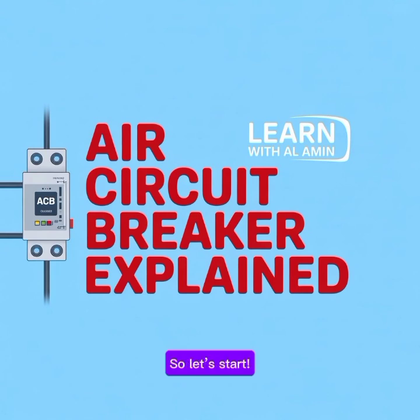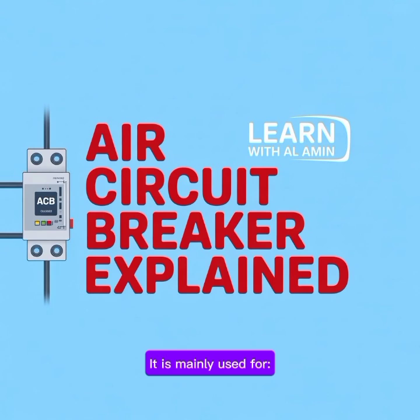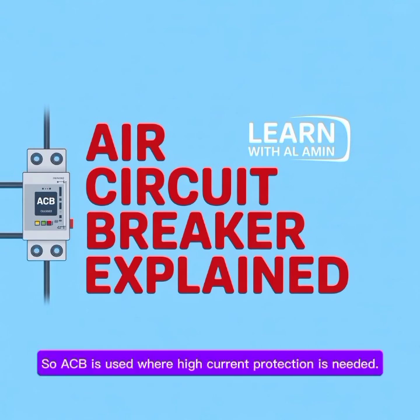So, let's start. What is ACB? ACB means air circuit breaker. An air circuit breaker is a type of circuit breaker that uses air as the arc extinguishing medium. It is mainly used for low voltage systems, high current applications, main incomer protection. Normally, ACB works in voltage range 415V, 690V AC, and current rating can be 630A to 6300A. So, ACB is used where high current protection is needed.